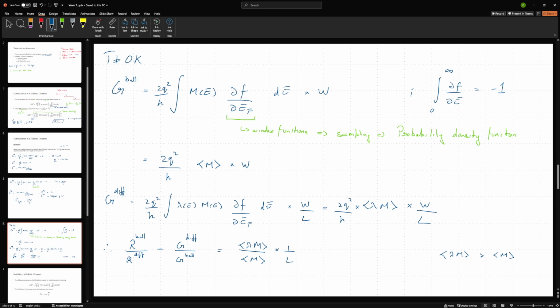When we are looking at geometries and device structures, what we should be focusing on is how long the channel is, how many modes the channel is allowing, and how to increase the number of modes. The straightforward strategy is to increase the width of the channel, because for a 2D channel, the number of modes is literally the number of half de Broglie wavelengths that will fit along the width of the channel. So if our channel length is increasing, we need to compensate by appropriately increasing the width so that ballistic conduction dominates over diffusive conduction.